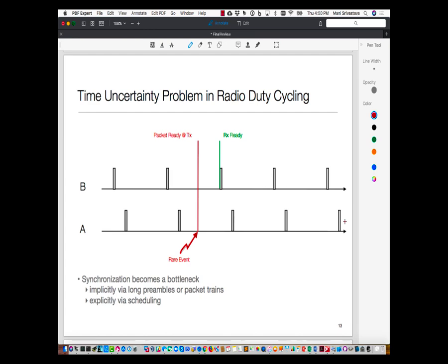Yeah. So why did you mention that they have to have the same period? Actually, they don't. But you can certainly work out a scheme using that. It's just usually done to keep the same period over the network, out of simplicity. So you're right, you don't strictly need it, but you need to have some way of knowing the recipient's wake up period. It could even be that all odd address radios have a 1 second period and all even address radios have a 1.5 second period or something like that. But it's usually not done. So we maintain the gap between B and A to be constant.